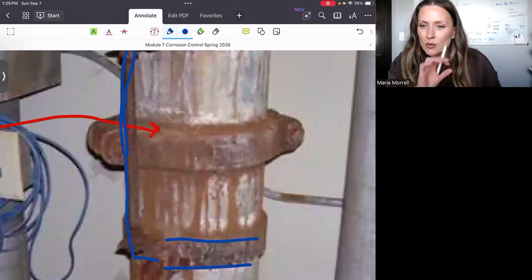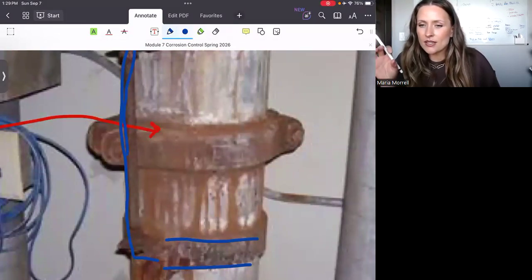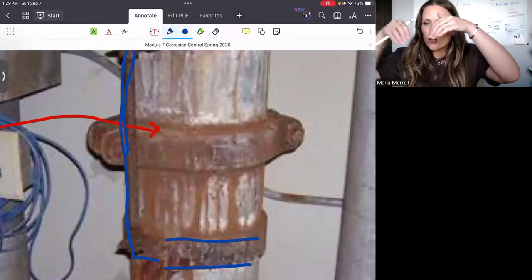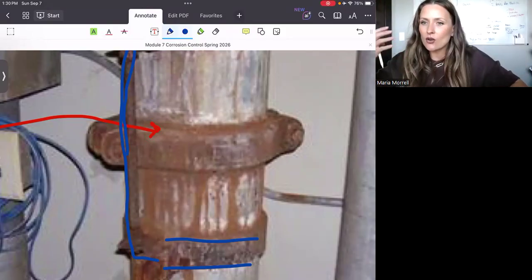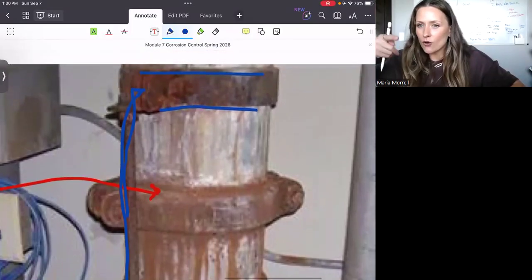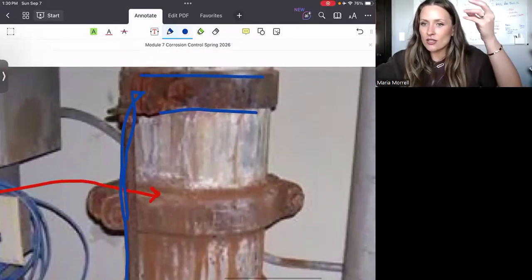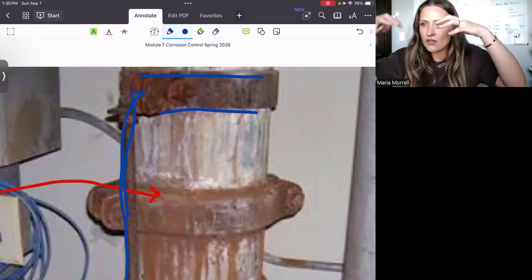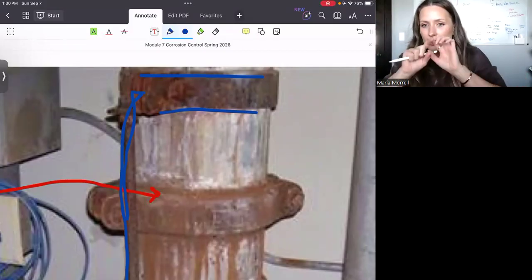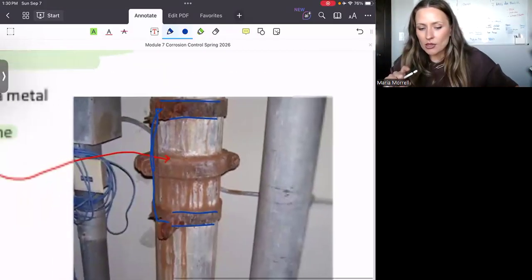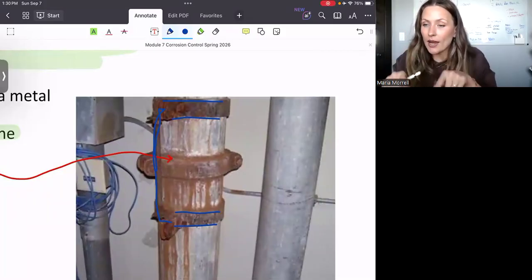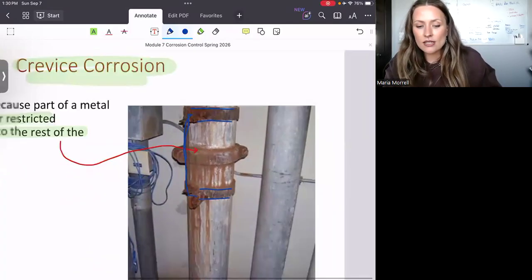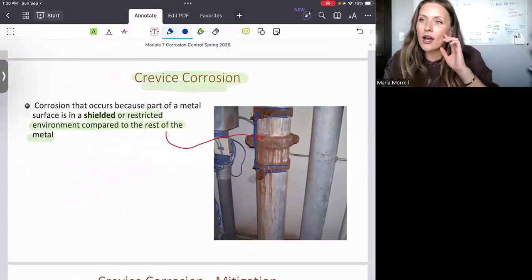The middle portion, there is corrosion in the crevice and a lot of outside corrosion. It's actually the corrosion product, the corrosion debris that falls from above because there's moisture, there's condensation, so it seeps underneath. But the two bands on top and below, you can clearly see that they corrode uniformly, right? Whereas the pipe is still fine, it looks just like the pipe to the right. So this is a good example.